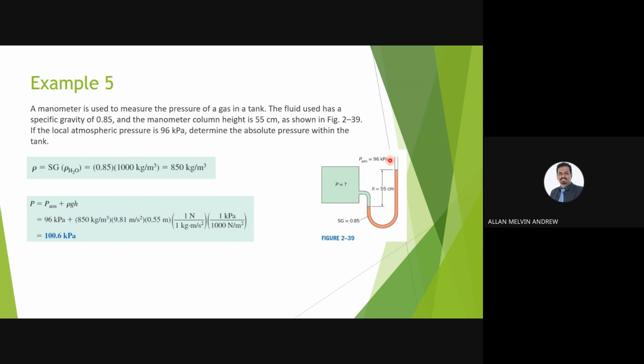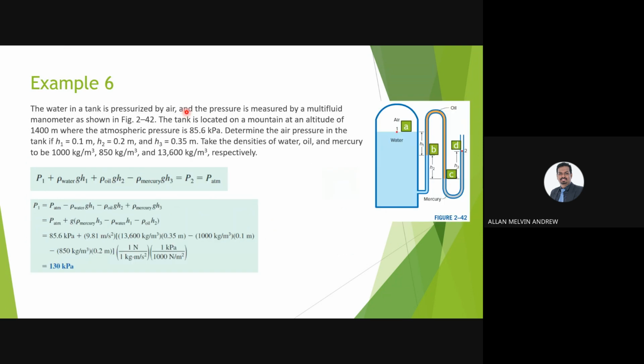All these are quite common questions, and quite easy because it is only a single fluid. If you understand the concept, you can do it. We are entering the last question for today. The water in a tank is pressurized by air. You have air here and you have water. We know that at point number 1, point A, the pressure of air and pressure of water will be the same, similar to point 2, point D.